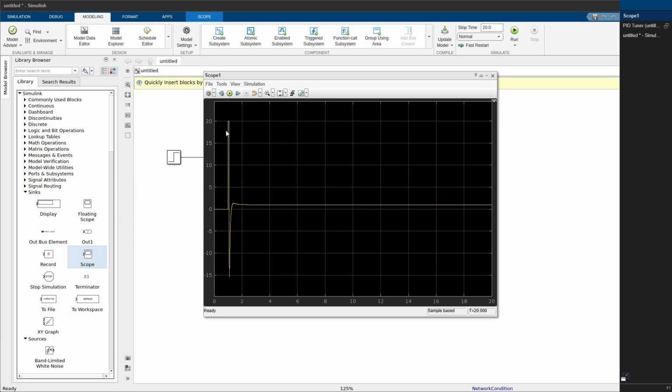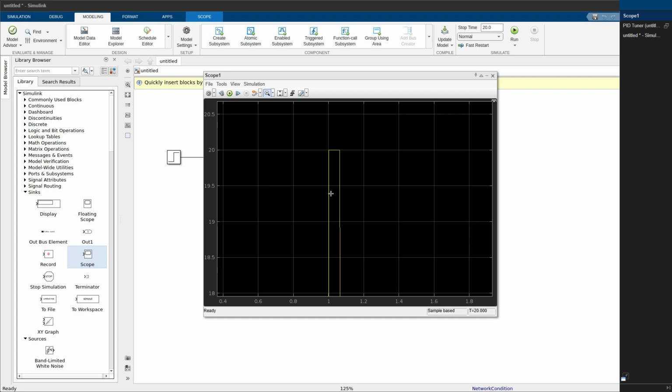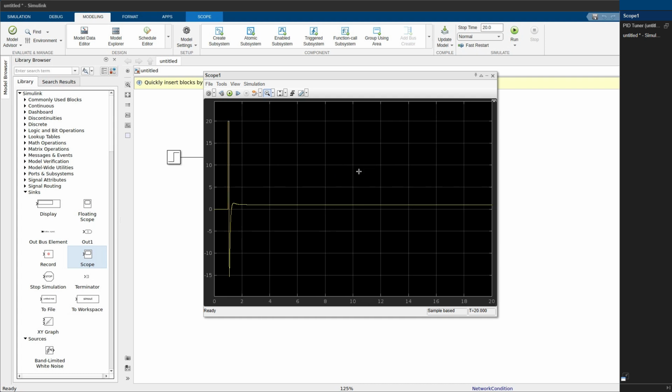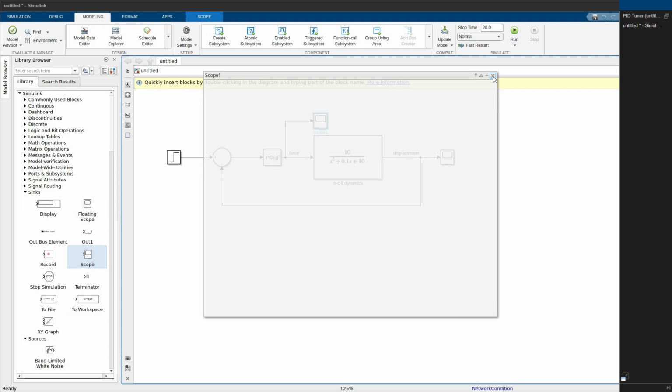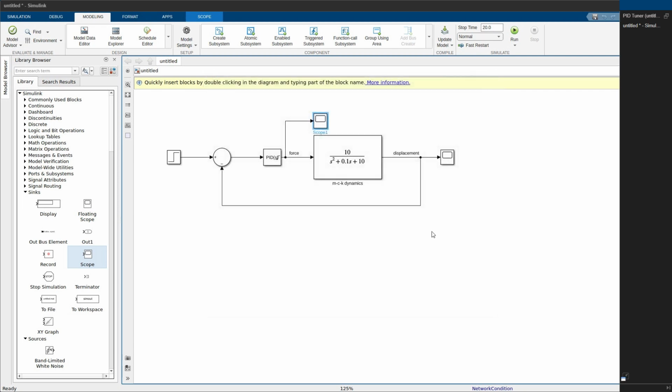You can see the force has been clipped. Whenever the PID demanded more than 20 newtons, it only passed 20, but luckily for a short amount of time. So this condition has been violated for a very short amount of time. Therefore the control performance hasn't deteriorated significantly, but depending on the circumstances, you may actually see instability because of the saturation effects in the system. So although you design your PID gains properly, because of saturation, the closed system may end up being unstable.